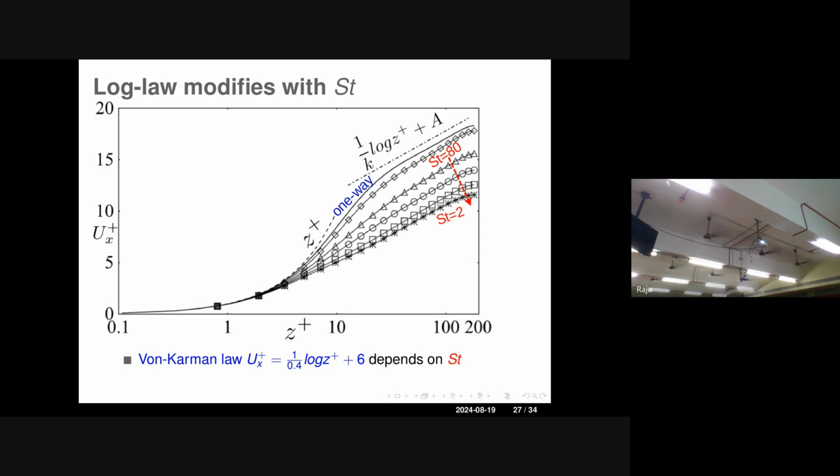Sir, I think you showed a slide where you had Stokes number versus volume fraction, with a column that showed one-way coupling, two-way, and four-way. So it's a combination of Stokes number as well as particle volume fraction that decides whether we need four-way coupling, two-way coupling or one-way coupling. So here we have two-way coupling. But it's low concentration, so you don't need particle-particle collisions.